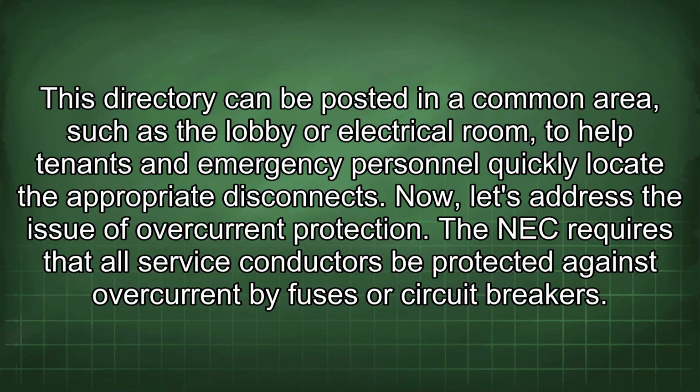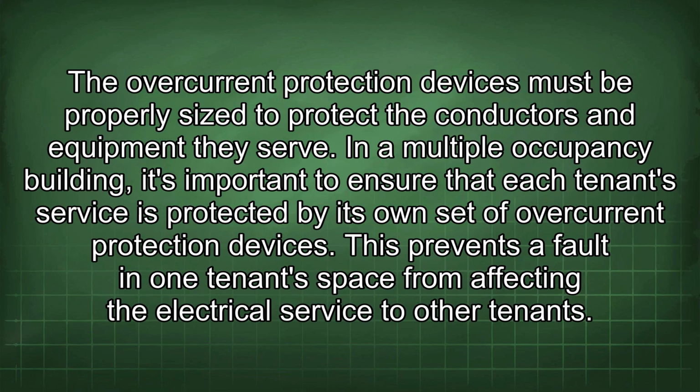Now let's address the issue of overcurrent protection. The NEC requires that all service conductors be protected against overcurrent by fuses or circuit breakers. The overcurrent protection devices must be properly sized to protect the conductors and equipment they serve. In a multiple occupancy building, it's important to ensure that each tenant's service is protected by its own set of